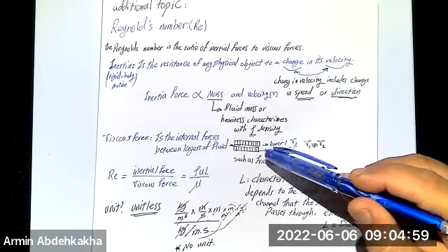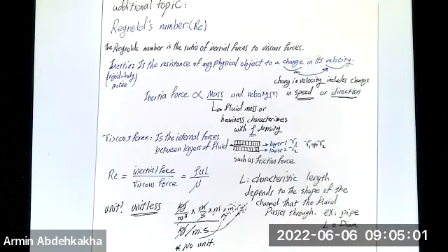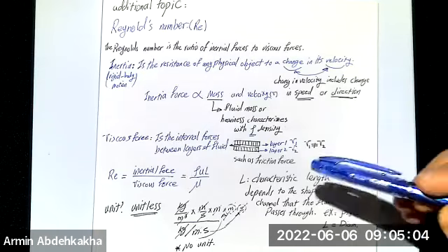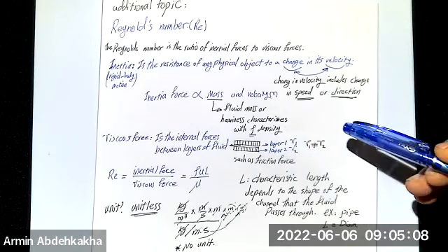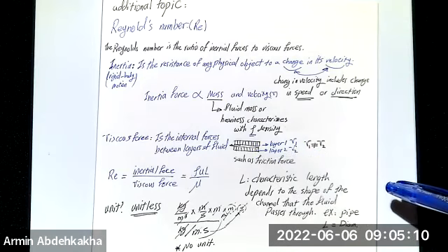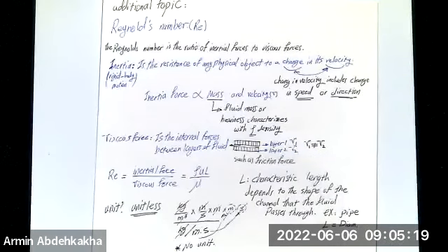If you have two layers with the same velocity, that's going to be different. Why? Because these two stick together and move together. That's exactly what happens when you have a fluid close to a constant plate, a plate that is not moving or is at rest. Then the fluid sticks to the surface and you have nothing like force between the two materials, the fluid and the plate.